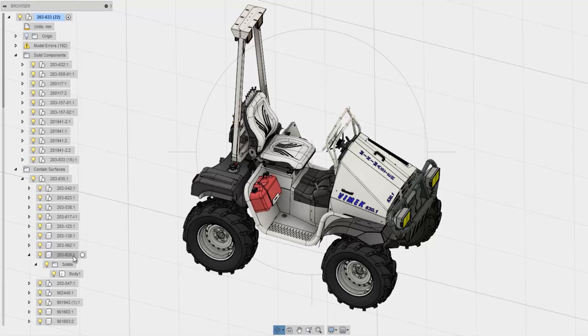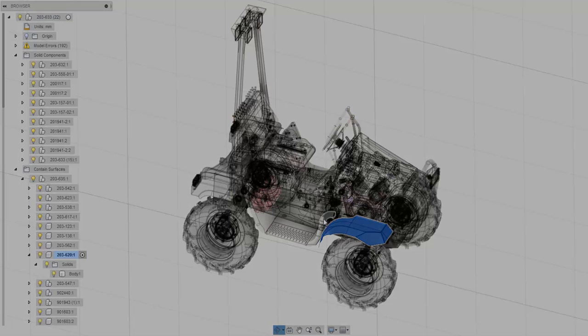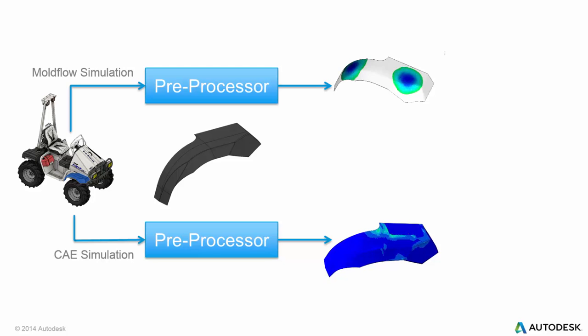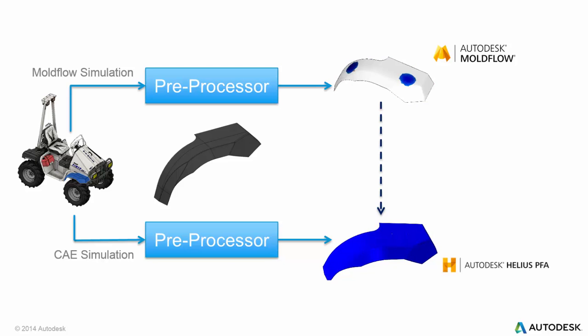One of the larger problems with structural simulations of plastic parts is using the manufacturing process to drive material properties of the structural simulation. Traditional analyses assume that the material properties are constant, isotropic, and homogeneous, which leads to a gross oversimplification of the material behavior in the model.